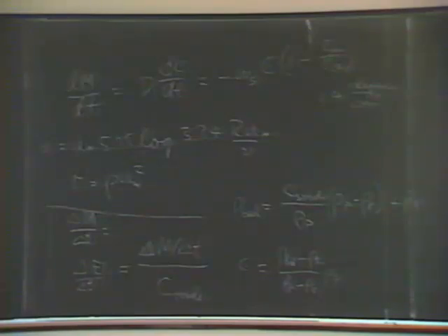So you can tell a lot by looking at the land before you ever get involved in a particular harbor. I just want to emphasize that before you get started in any particular problem, it's a really good idea to look over the area carefully, get some idea, find out what the tide range is, find out what the freshwater outflows are, if there's freshwater outflow, and what the wind patterns are, and so on, so that you don't overlook some significant factor in the design process.